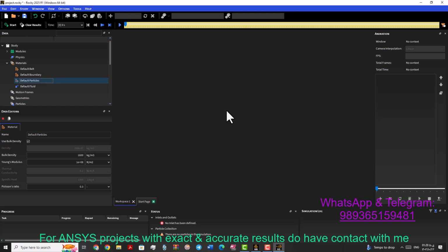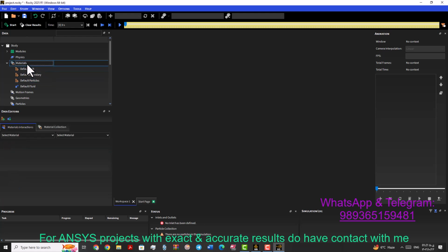We have an interesting point here: in ANSYS Rocky you can simply design and simulate a conveyor without wasting so much time, and you can have a good approximation of how your conveyor should be for particles. And then after the approximation, you can go into details with CAD software and finalize your design.